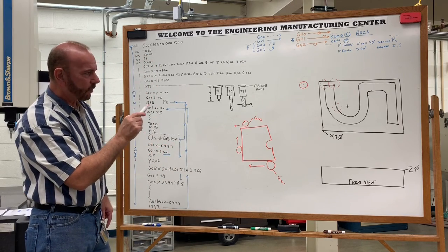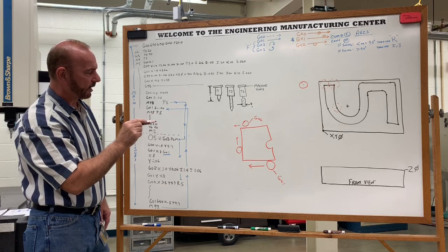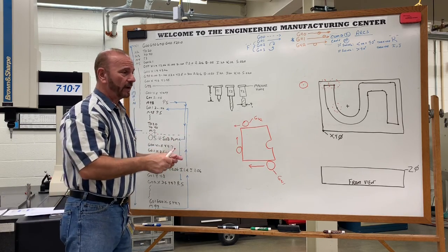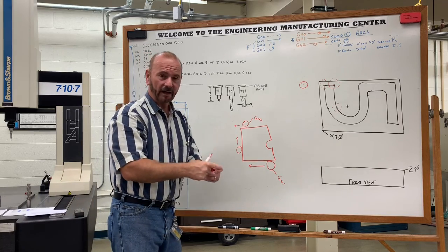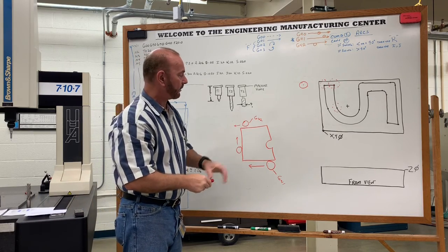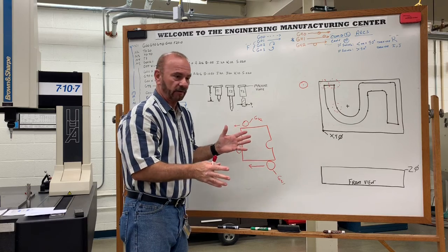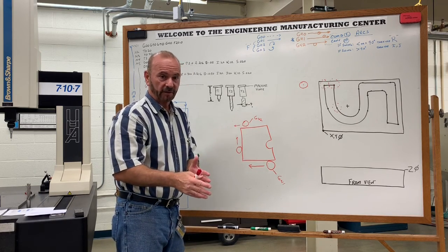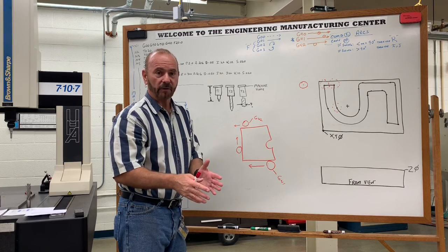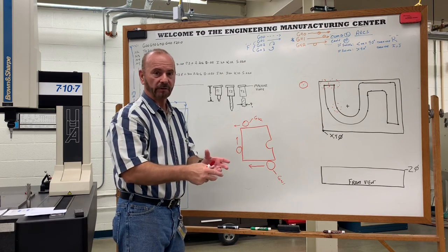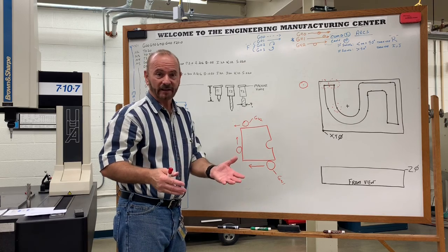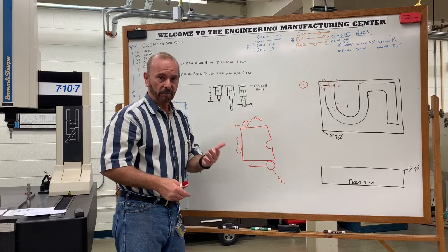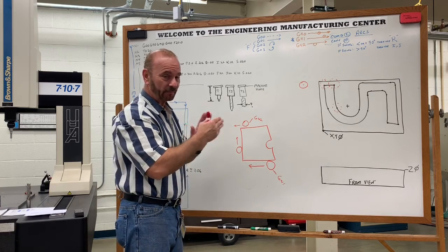But I want to first go over what happens with cutter compensation. Cutter compensation doesn't just occur. A lot of times the cutter's already engaged in the material, and what we don't want to have happen is that when we turn on cutter compensation, the cutter immediately moves left or right. That could destroy the cutter. It could interfere with part of the contour, and it could violate, let's say, a wall of the part. So cutter compensation requires what we call a ramp-on move and a ramp-off move, a distance of travel.